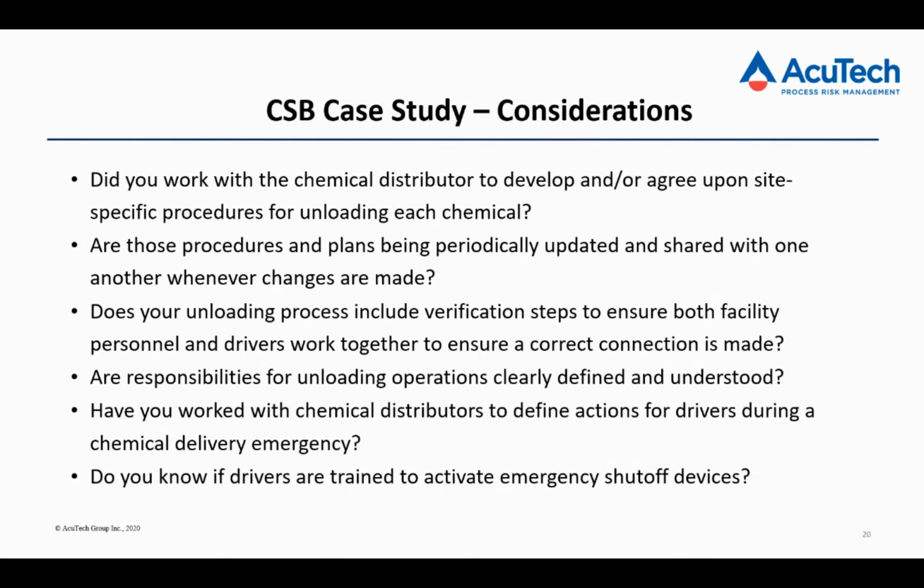Are the responsibilities of that unloading clearly understood? What is in the operator's domain, and what are the driver's duties? And in an emergency, are the responsibilities clear? Do the truck drivers know that there's an emergency stop button located 30 yards from the unloading point on a post? And do they know how to activate that and how to maybe get help if they need it in the event of an emergency? So these are just some considerations, things to think about.